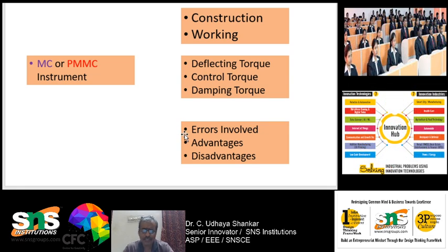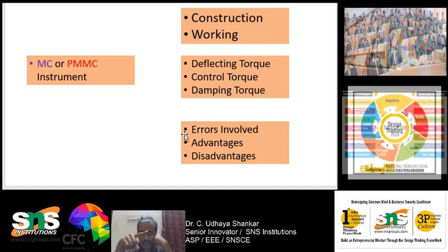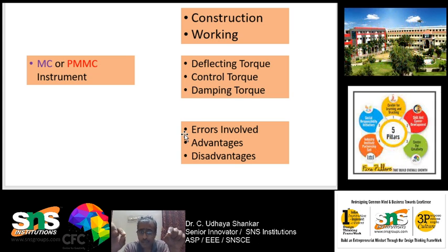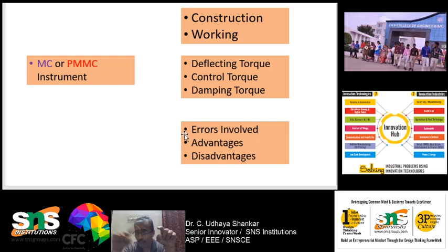I just want to convey here that this PMMC works on the motoring principle. What do we mean by the motoring principle? In the case of a motor, whenever a current carrying conductor is placed in a magnetic field which is produced by the permanent magnet, then the coil will experience a force and hence the coil will move. That is called the motoring principle.